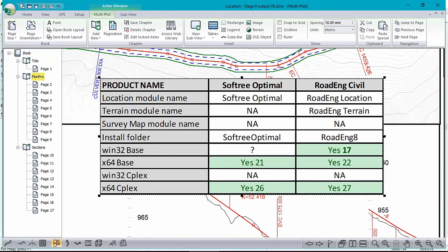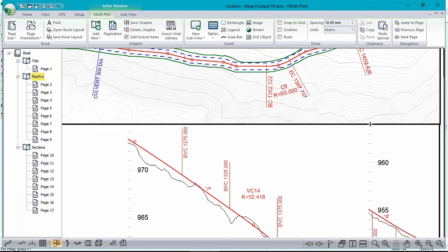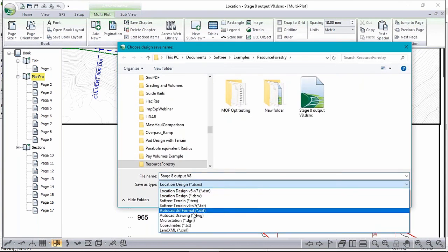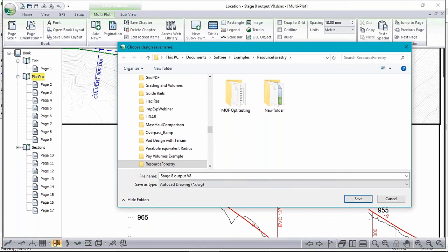For groups who prefer AutoCAD style output, sort of, you can export our multiplot as CAD drawings, and you can save as PDF too, which might be good enough by itself. But yeah, we've still got the file, save as, choose DWG. But I have a feeling that what happens when you do this is you get a bunch of model space drawings, one for each page. So I'm not sure if that's going to be very useful for building a CAD paper-space document. But it is available.